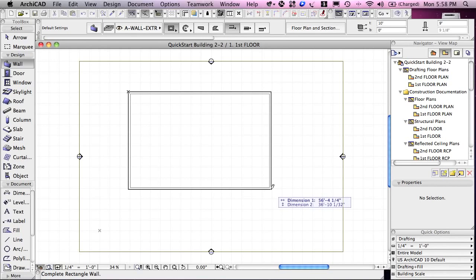The other line is determined by the construction method of the wall. In other words, is it left, right, or center, or some other variations where there's an offset to the face of framing. This other line is determined then by the construction method and the current settings of the wall tool. So if the wall tool is set for something thicker, that other line will be further away. And if the wall is set for more complex composite with multiple skins, we'll see that being drawn as well.